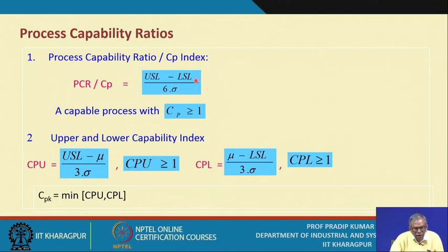With respect to that quality characteristic, you must know what USL and LSL are. These two values, the specification limits, are prescribed by the designer. So, you must have these details. When you look at the engineering drawing, you will find the specification limits are given, and you will also come to know the nominal dimension, and it is a double specification limit case.